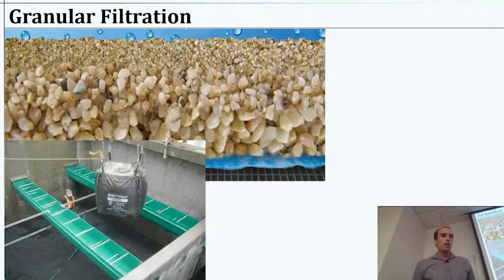So the granules themselves are actually fairly important. We want to design a system where we have pretty much the same size material. Sometimes we might have a couple of layers, maybe something like activated carbon or anthracite, and then just sand, or maybe sand with some special coating to try to adsorb stuff better.